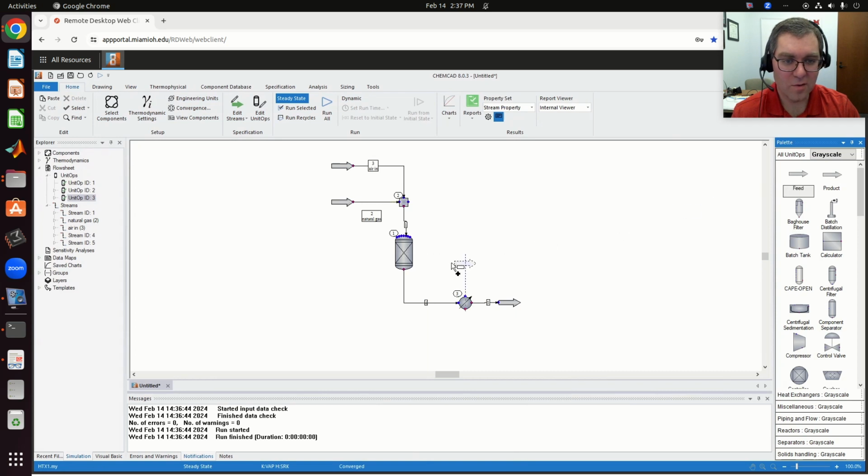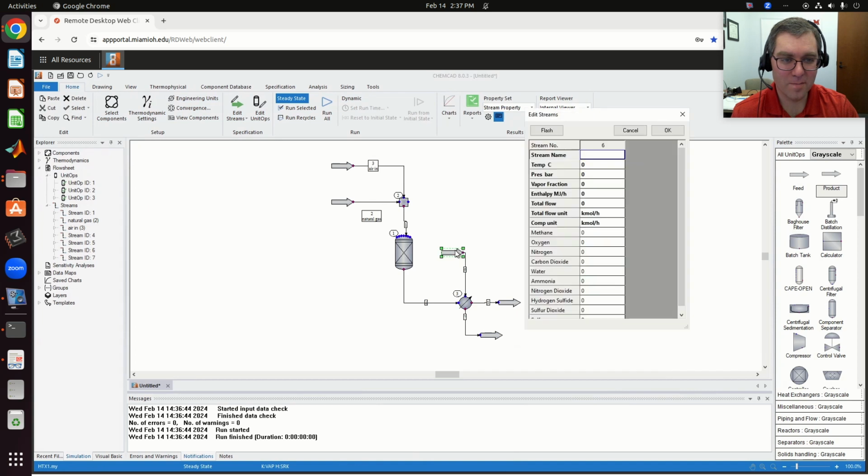If I want to think of that in terms of steam generation, let's see. And you could always add a controller to optimize this. Okay, but stream 6, I can make, say, pure water. And let me say I start, crazy, with 500 kilomoles per hour at a temperature of 20 degrees C and 1 bar.